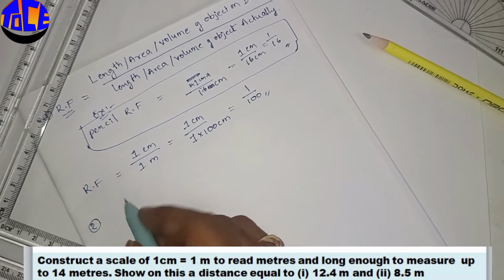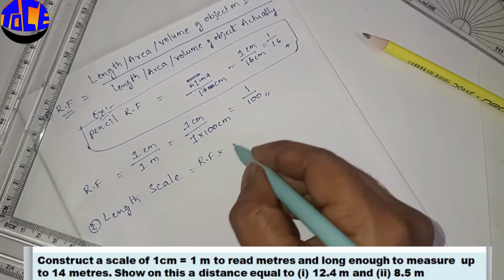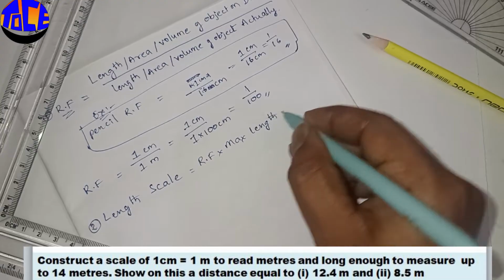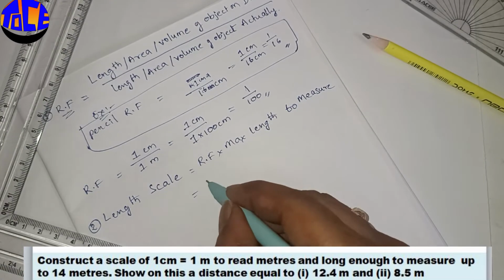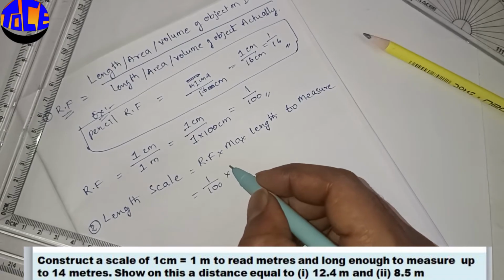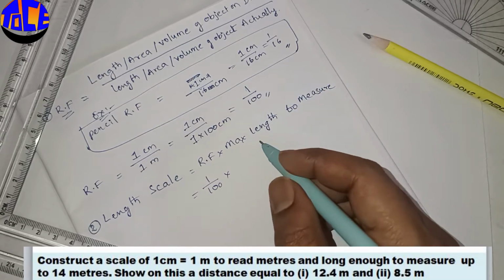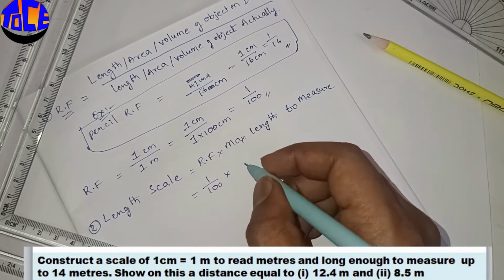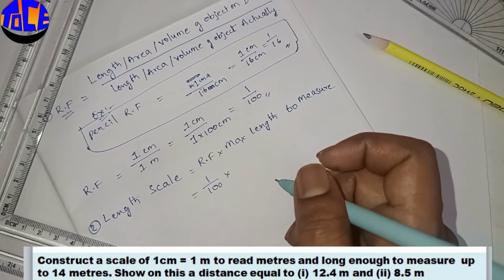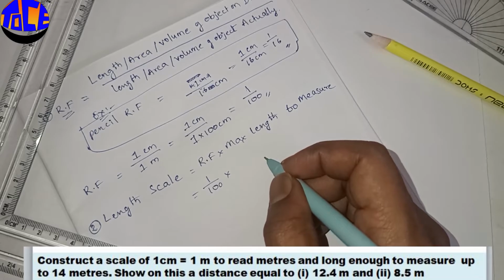So in the second step, we need to calculate what is the length of the scale. Length of scale is equal to RF into the maximum length to measure. So what is the maximum length we should measure with that scale? RF we know is 1 by 100. And coming to the maximum length in the question, he has to construct a scale long enough to measure 14 meters. So 14 meters will be the maximum length of the scale. And one more thing, if you observe this question, the maximum value you can observe is 14 meters itself, right? So that will be the maximum length. He's asking to measure the scale up to 14 meters.